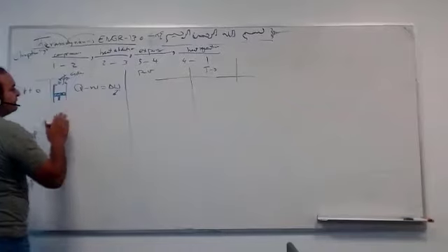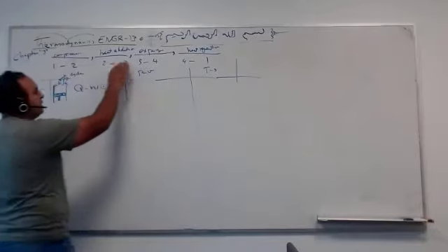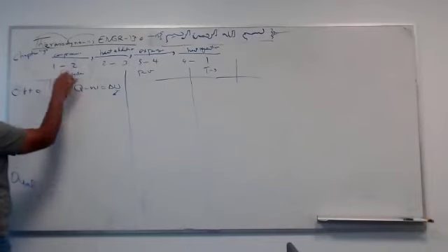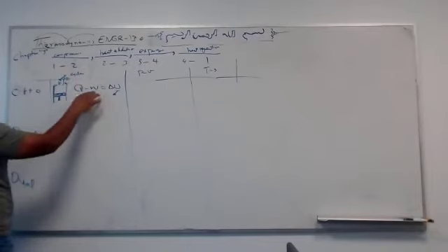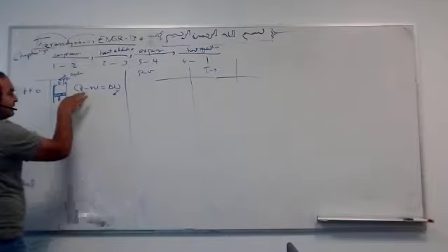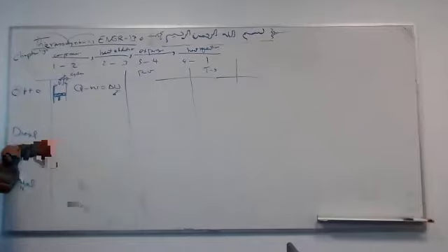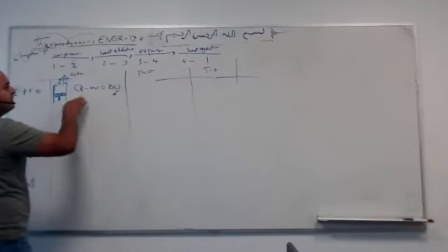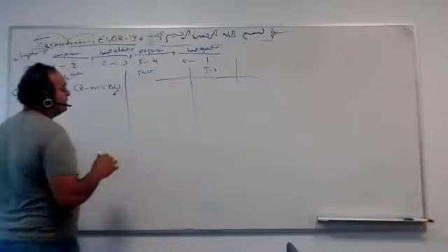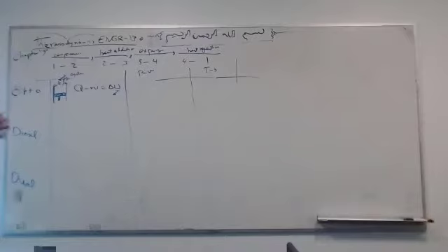So Q minus W equals delta U. That's always correct for all of these cycles. So you have here either Q or W. For example, here, what do you have? We have W. This is compression. How about heat addition? We have heat, Q. And we don't have W, or we have W, but it is constant due to constant pressure. And expansion, do we have W or Q? W. How about the heat addition or heat rejection? Q. We call it Q high and Q low.